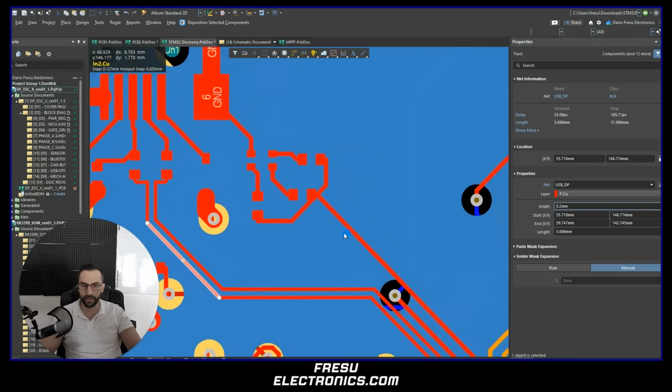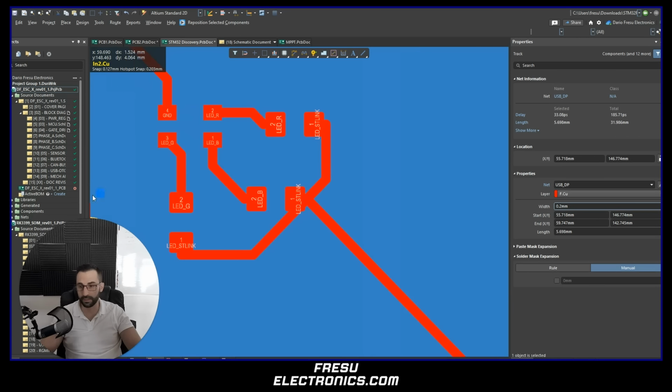So let me show you a point where we can have this issue. We can have it in here, where we have a signal going in this direction, and then here you see a split. So what happens in this split? The signal is going to see that this point is 50 ohm. So this is 50 ohm. What's the impedance at this point? Because now the signal will come to this point and we see that here the impedance has changed. You will have to decide what to do in this place.